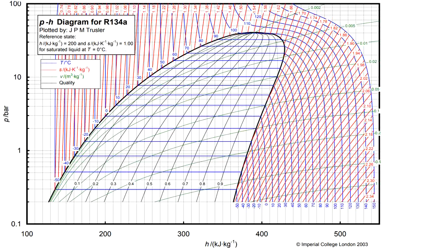So for our cooling box with the cooling cycle, we had the temperature of evaporation, the temperature in the evaporator at minus 20 degrees C. The cooling box was minus 15 and 5 degrees temperature difference.